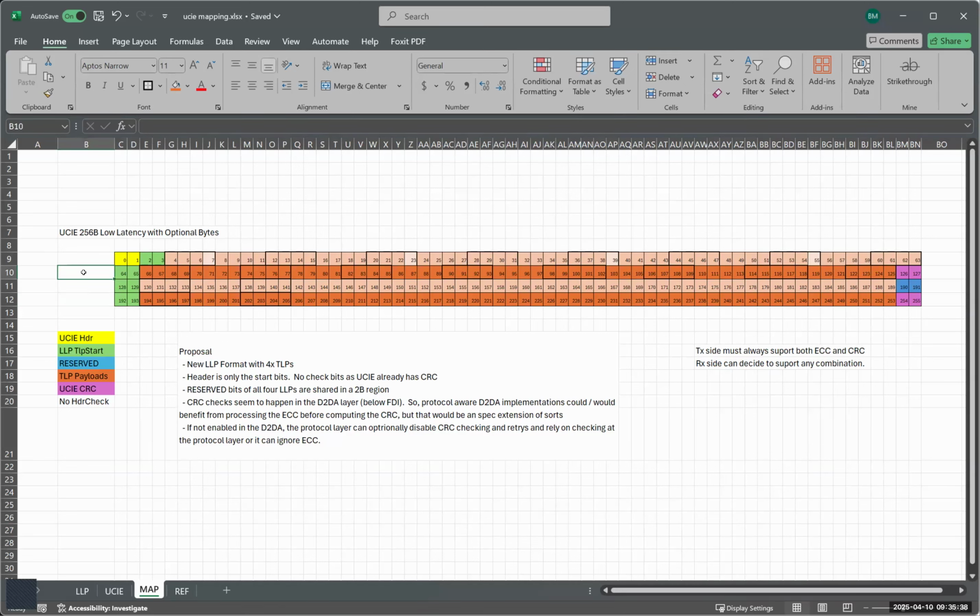The second fragment has a half granule, and then the rest of the granules are half aligned for the next couple. The reason for that is so you could get the header bits out the interface first before the rest of them, so you can do ECC processing properly.